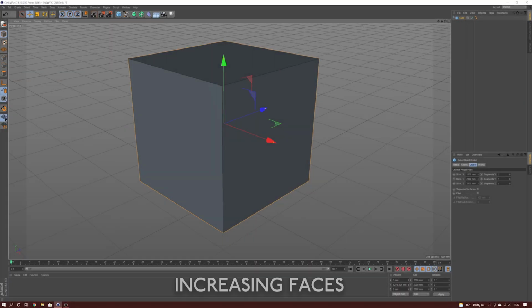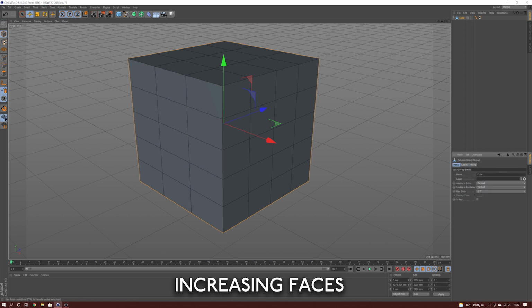Every object you create can be defined and edited in three main ways. We're going to start with the default cube and divide its sides up into segments we can edit individually. You can choose to edit the points, edges or faces. These can either be moved, rotated or scaled. Simple objects with few faces or points are quick to render, but this resolution means that they're not so good for curved surfaces and creating smooth 3D prints.